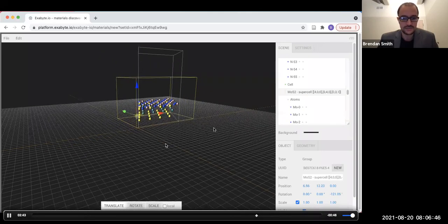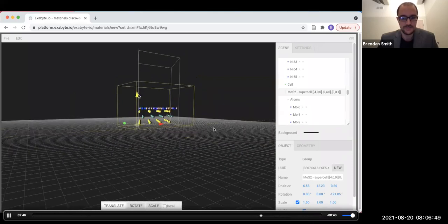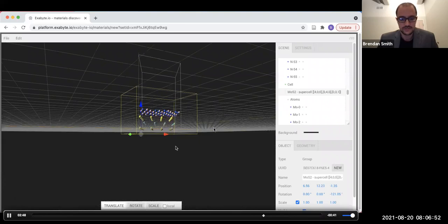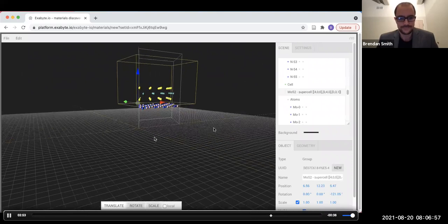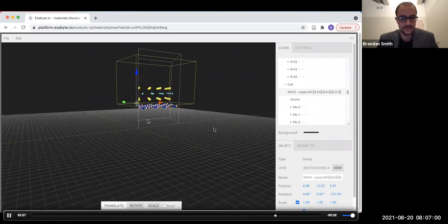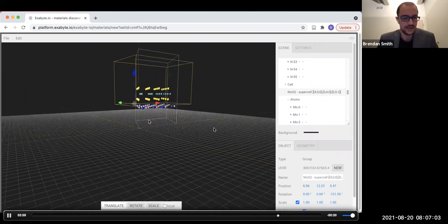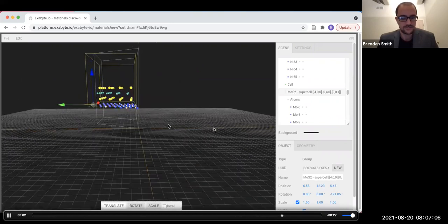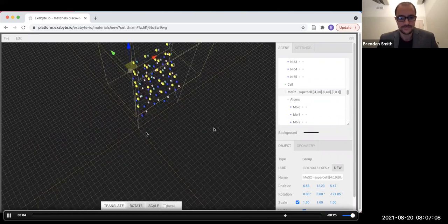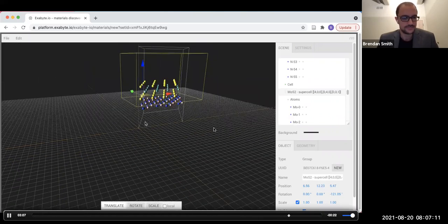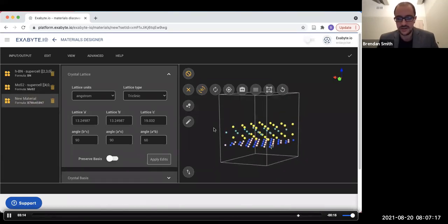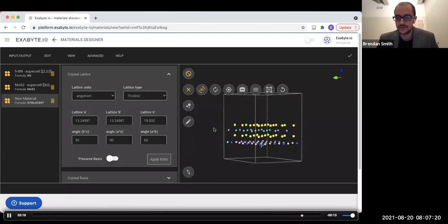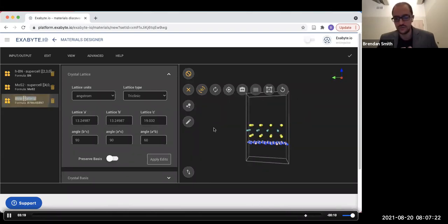I consider placing the molybdenum sulfide below, but I end up opting to place it above. If you want to add a little more than I do, you can simply move it a little higher. So here I end up being satisfied, and I'll go ahead and save this. Okay, so now I simply am going to check out my new material and then rename it. This one was slightly non-trivial due to having to make the root integer supercell of hexagonal boron nitride.